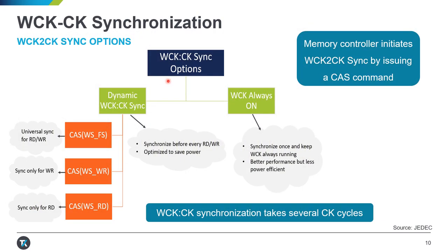There are two options which a controller can use to synchronize WCK with CK. First one is dynamic, and second one is WCK always on mode. In the dynamic mode, WCK needs to be synchronized with CK before each and every read and write operation. It's less power optimized. It affects the performance as well, since WCK synchronization takes several clock cycles.